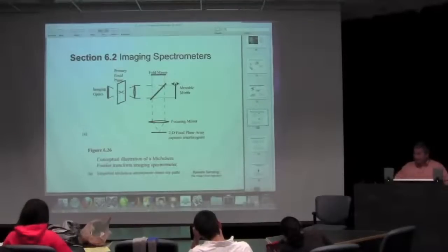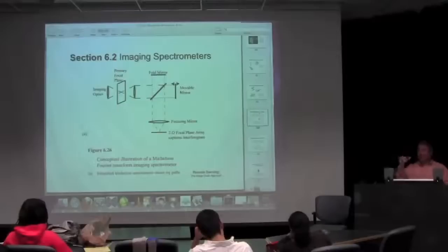Yeah. So then I would scan backwards. That would be another interferogram. Then I'd scan this way, another interferogram. So when you watch the data coming off this, the interferograms flip back and forth, so you have to reorient them before you do the inverse Fourier transform to get your spectra to come out correctly. But because this is on a moving platform, you're going to have problems.